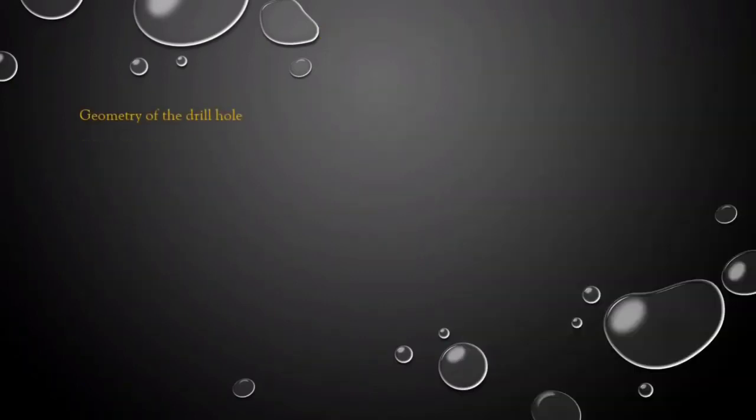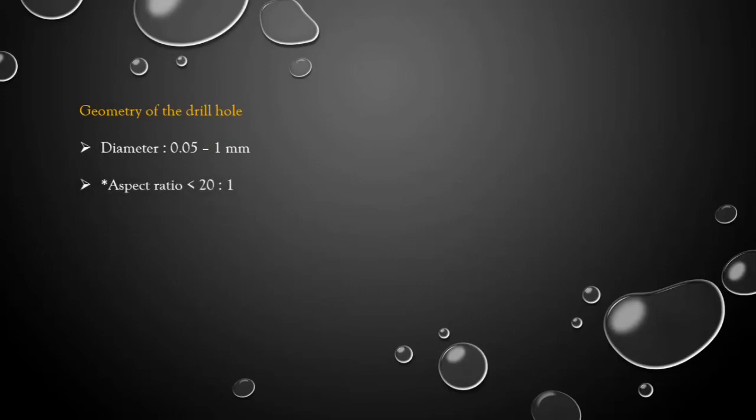Next, the geometrical structure of the hole made by single pulse drilling. The diameter of the drilled hole is 0.05 to 1 millimeter. Aspect ratio is less than 20:1. Then the duration is less than 1 second. What does the aspect ratio actually signify? It is the ratio between hole depth and hole diameter.